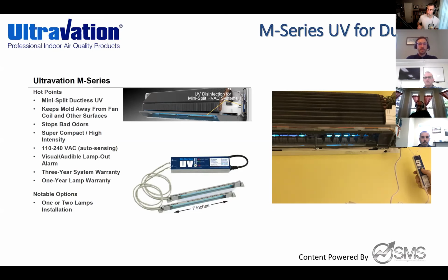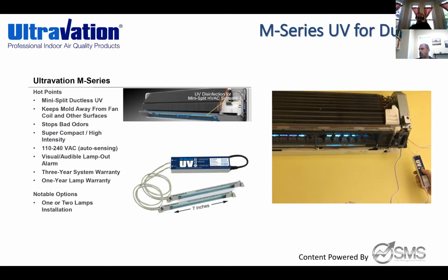These do need to be replaced. The bulbs need to be replaced every year anyway as well. So if you're going in doing your annual maintenance, then swap out the bulbs on these. It does have a 3-year system warranty on it. You do have the option of 1 or 2 lamps for installation. They come with 2 lamps no matter what, but if you have an application that you can only get 1 lamp in, then you can just do 1 lamp.